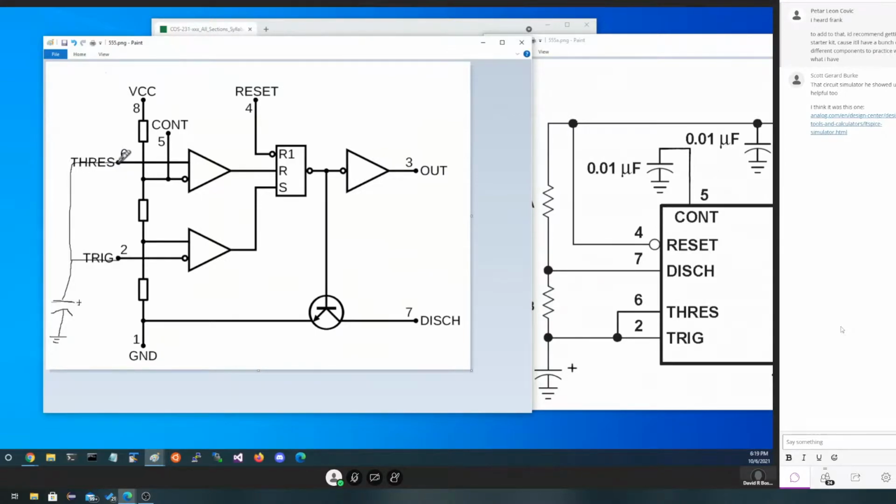Now, additionally to that, in the range after we've hooked them together, there are two resistors, one here and one here. The top resistor here is hooked to VCC. The middle of this is actually hooked over here to discharge. Now, I don't have any good way to route it there, so I'm just going to jump over that and head over here to discharge.